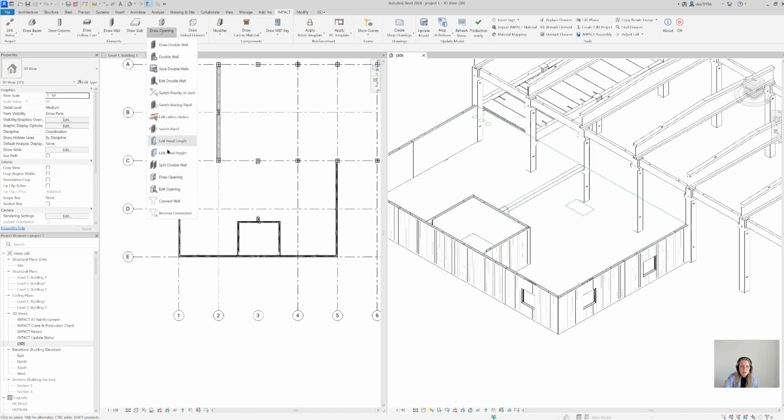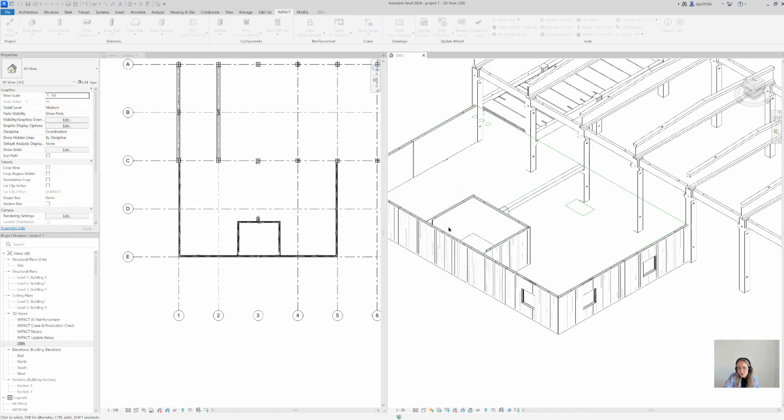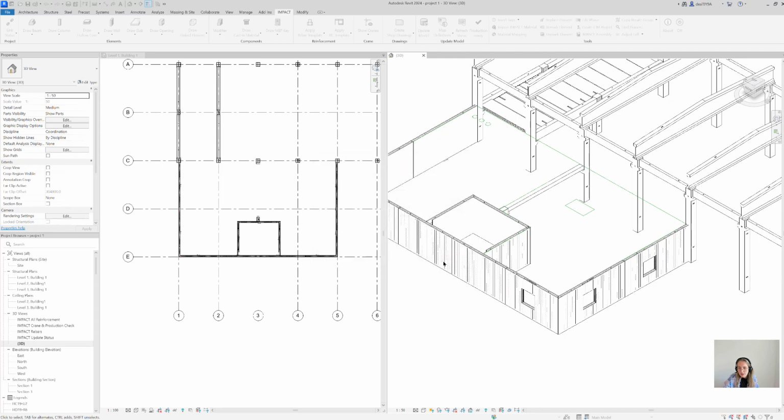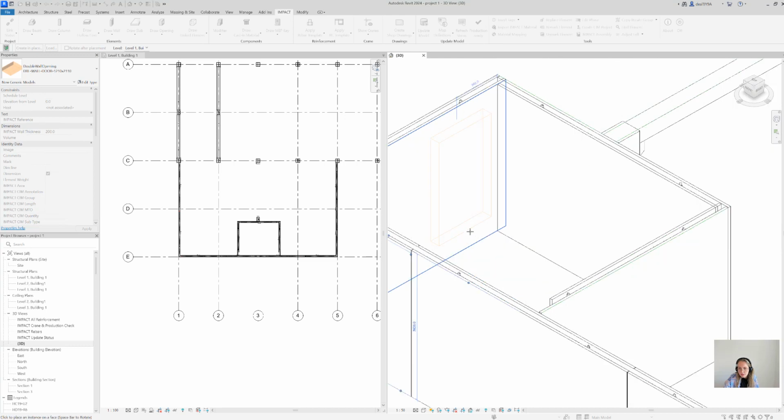I'm going to do a door, so it looks a little bit better when we present the final outcome. I'm going to do a door, and I'm going to keep the settings. I'm just going to make it 2 meter high, over 2 meter high. Say okay. And the insertion point is then the middle of the lower point. Can I do a door in here as well?